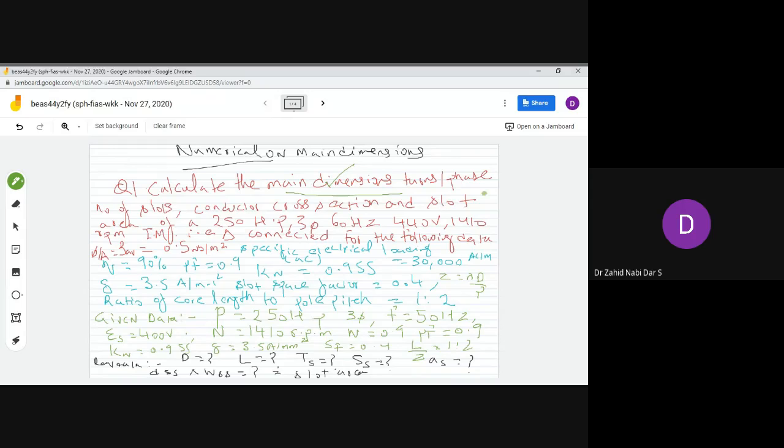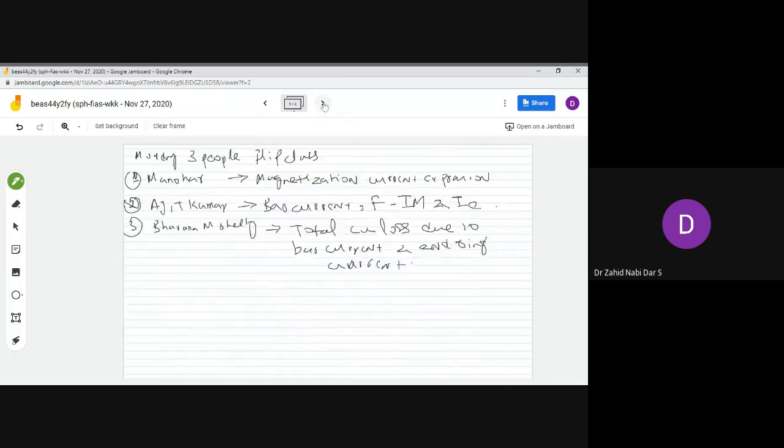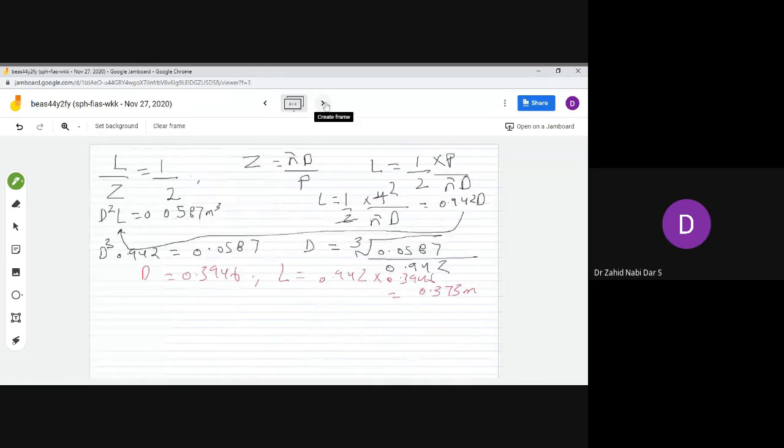Now you have to move on to the turns per phase. In order to get the turns per phase, how do you go about this problem? One thing that has been mentioned is your average flux density. Before going to the turns per phase, you know that if you write the EMF equation, Es is equal to 4.44 F phi m kWs into Ts.